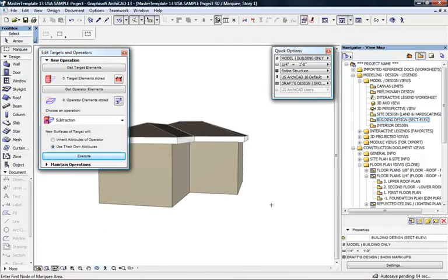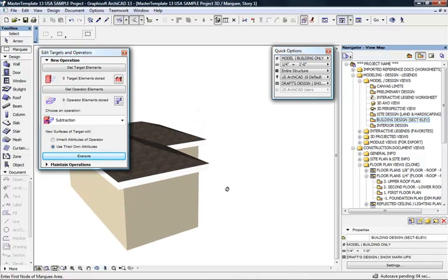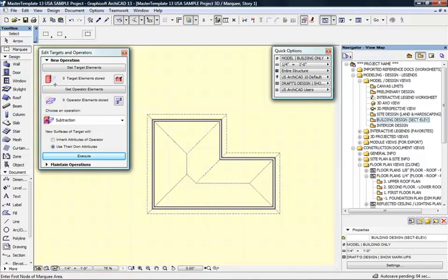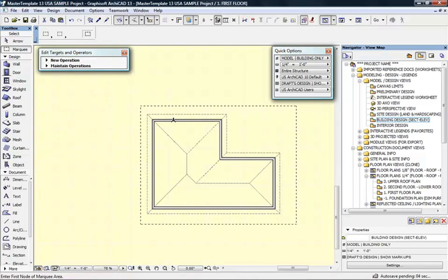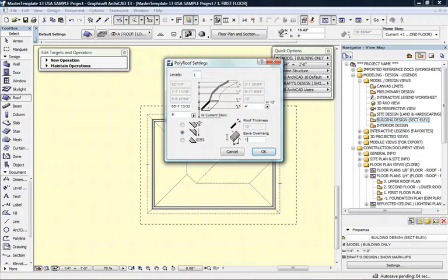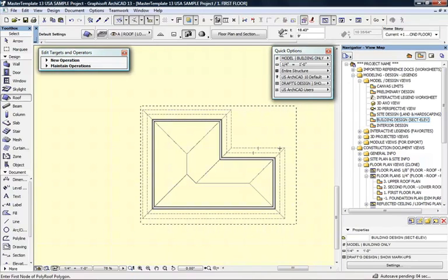And you can see here's the basic building shape. And I'll close up the solid element operation so we have more of the screen to look at. Then I'll go back with the roof tool, perhaps in this simple case. Instead of copying the roofs one at a time, I'll just recreate the roof structure, but this time with a 2 foot overhang. And I might as well just drop it down to the 8 foot 9 that I know I need. So now we've got these outer pieces.